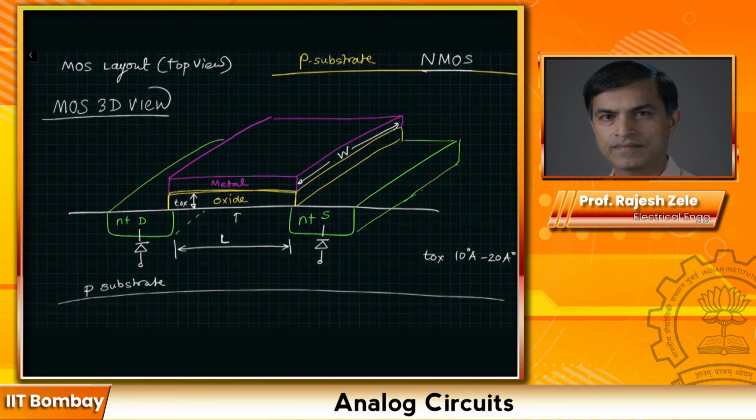You must have heard different numbers like 28 nanometers, 65 nanometers, 90 nanometer technology. This L is what is being described over there. If L gets shorter and shorter, then we can pack more and more devices on a chip. And if you remember, in the first lecture when I told you the story, when I was building my own devices, we had 5 micron technology in IIT Bombay at that time. And now we are talking about 5 nanometers. So that's 3 orders of magnitude of change in the device sizes that we have seen.